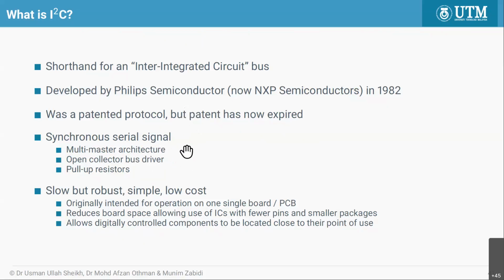When you have an open collector, that means when you want to connect components to the bus, you must have a pull-up resistor, but you can add and remove devices from the bus quite easily because it's open collector. So it's not like if you have 3 there, you cannot add to make it 4 or remove to make it 2 components in the bus.